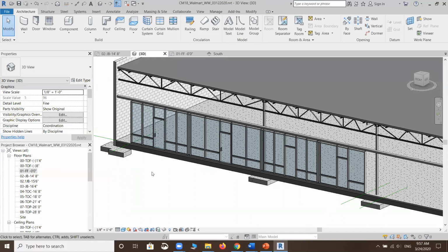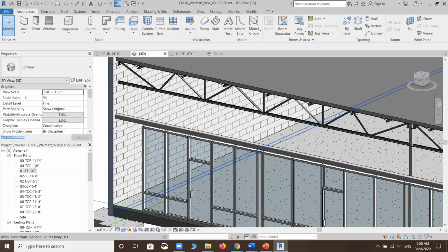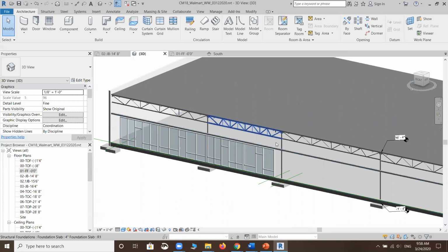Okay, so that's all we have today in terms of placing the component. So a quick recap of what we did today, right? We placed this stretchable framing component which we had left from last session, which is this hollow stretchable steel, which is 6x6 by 5/16, on top of the curtain wall, and we placed the curtain wall system itself.